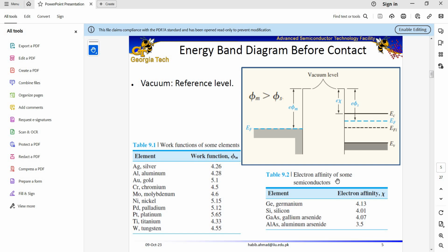And secondly, we talked about non-rectifying junctions. Non-rectifying junctions can allow current to flow in both directions. So, in today's lecture, I'm going to demonstrate Schottky junctions and non-rectifying junctions for both N and P-type semiconductors. Our example is based on gallium nitride material, for which the band gap is 3.4 electron volts. Let us first consider the example of an N-type gallium nitride based Schottky diode.